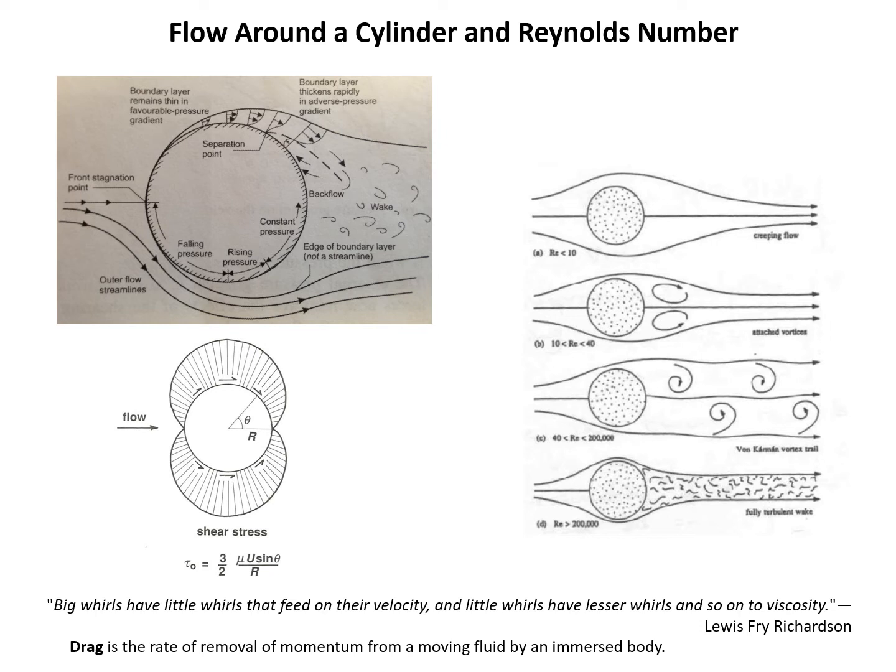Or if this system is working in a very slow flow regime, then the Reynolds number will be very small. If the viscosity is high, the Reynolds number will be small. So the characteristic length, the velocity, the density, and the viscosity, that combination determines this Reynolds number. And the Reynolds number then determines whether you have this separation of a boundary layer.